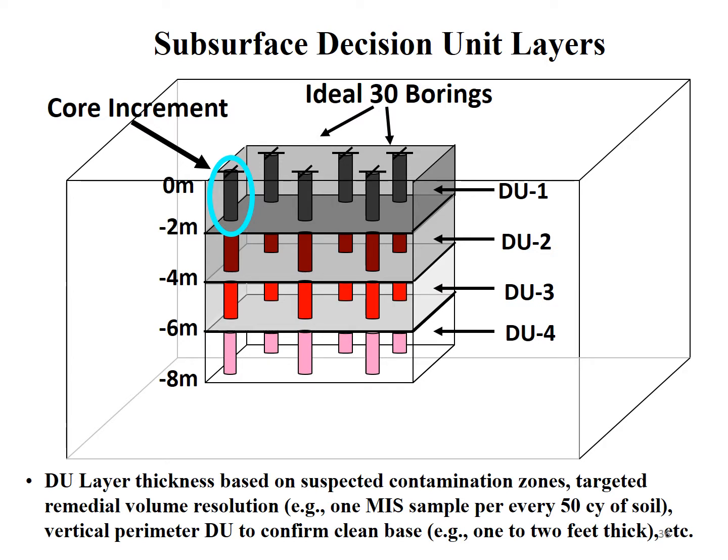Also, if VOCs are targeted in the subsurface investigations, this presents additional challenges that must be well planned for: to collect multi-increment samples from the cores into methanol, and to closely coordinate the timing of core extraction and core opening by the driller in order to limit the time the core is on the surface and open before subsampling, to prevent the loss of VOCs.